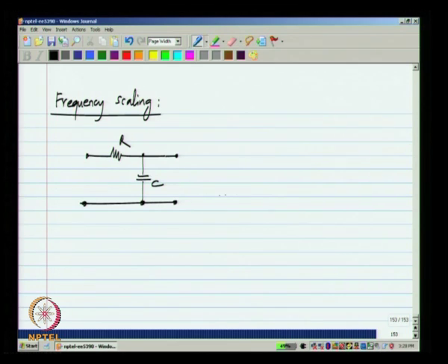We know that the output noise variance is kT divided by C. Okay. Please keep in mind, previously in the noise scaling part we were talking about the noise spectral density. Okay. And here we are talking about the variance of noise or the mean square noise. Now, the two are related, but not exactly the same thing. So, please be aware of what is being reduced when we say that we reduce noise. Okay. So, the mean square noise that we get is kT by C, and we can change the bandwidth of the circuit.